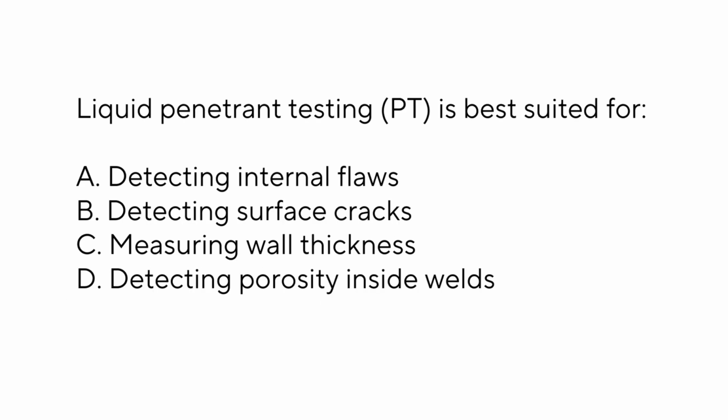Liquid penetrant testing, PT, is best suited for: A. Detecting internal flaws, B. Detecting surface cracks, C. Measuring wall thickness, D. Detecting porosity inside welds. Answer: B. Detecting surface cracks.